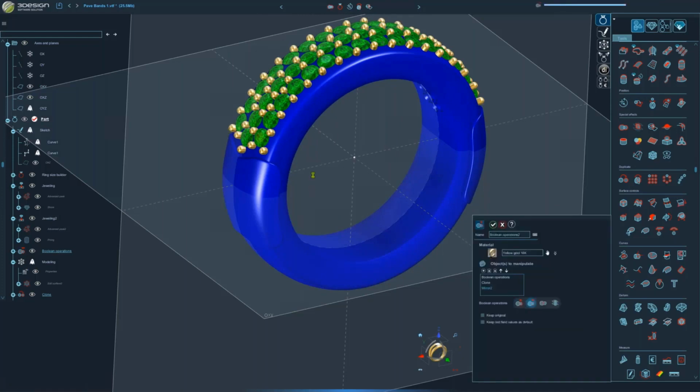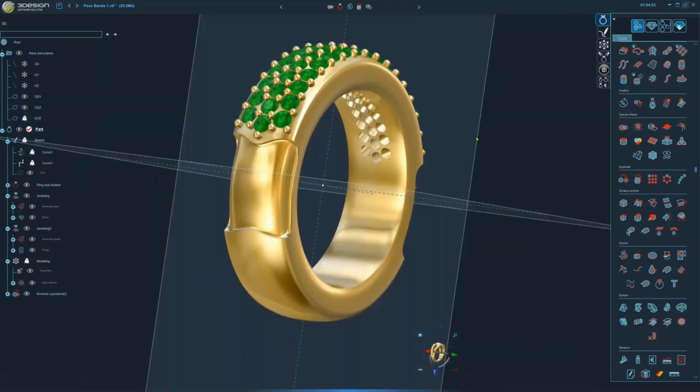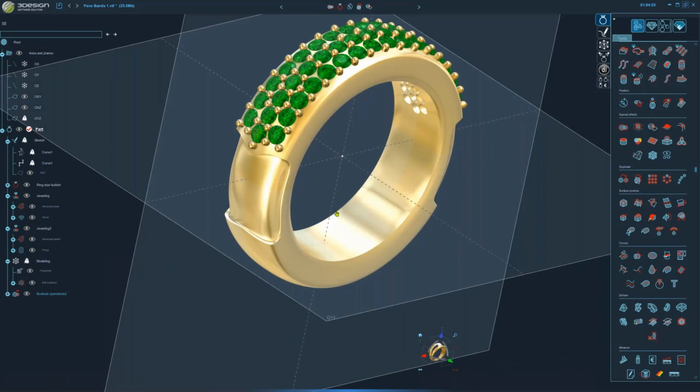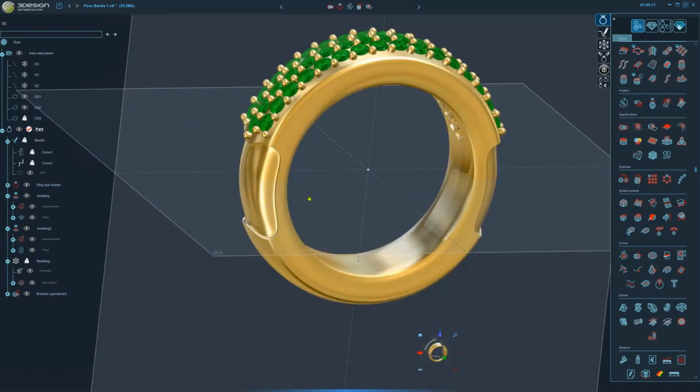And now we've got a spot where when we cast that separate little piece, it's going to be able to fit back into the ring. You may even scale that up a little bit if you want to give yourself a little room, or you can leave it as is. When you're fabricating the ring or putting the ring together, you can do that by hand and just kind of clean that out if it's not fitting in as a glove or like a puzzle like it should. Up to you. You have to kind of play around with how much shrinkage you have in your casting processes. So we got our two cutouts.